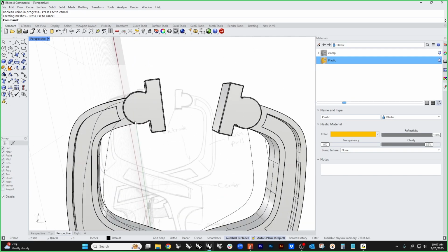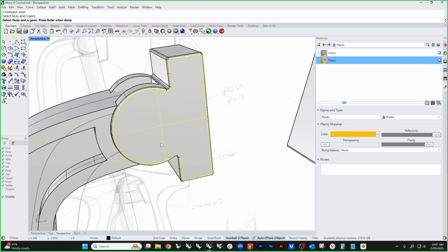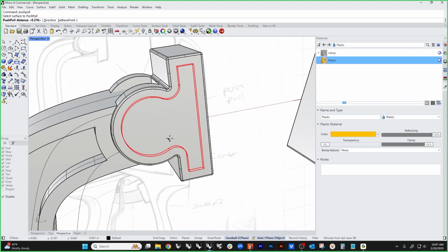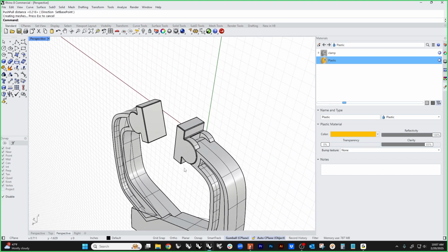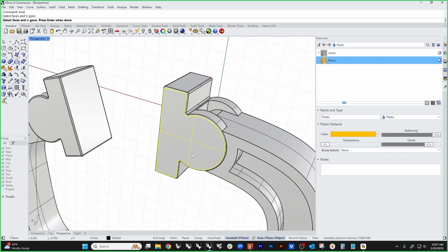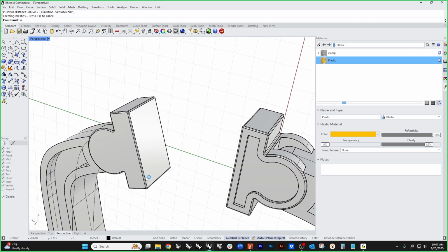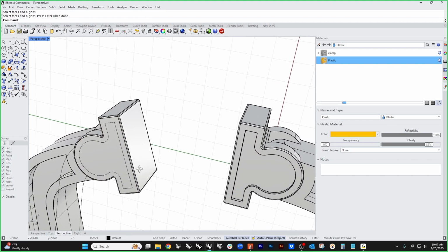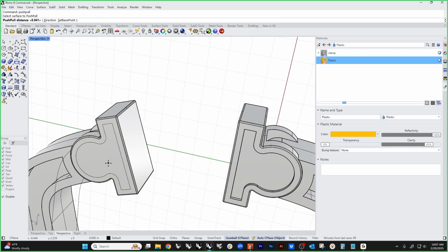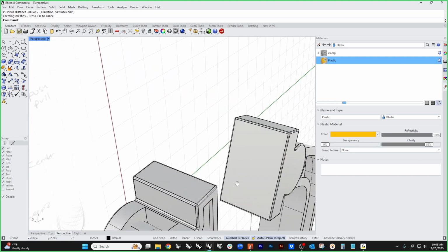All right, let's make this guy just a little bit more interesting with Inset. And I'm going to do this as a through point, and we're going to just add an additional little detail in here with push-pull, just because it looks cooler. And the nice thing about Inset is it remembers your last value, so does push-pull. So if I run Inset again and then just right-click, it gives me the same Inset. If I run push-pull again and I click and I drag in or out, if I go in, it's red. And then I just right-click. I don't left-click to set it. I just right-click. It'll give me the last one I did.